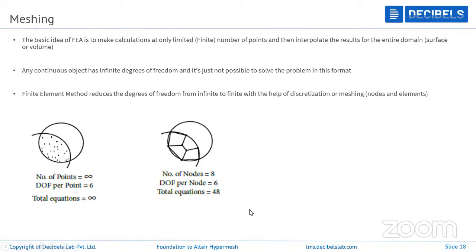We did this in our academics, in the finite element subject, how to calculate the number of equations for a particular surface. When working with truss or bar components, we calculated the number of degrees of freedom, the stiffness, and extracted natural frequencies, all based on the number of nodes and degrees of freedom. Likewise, the software works in the same way. It will calculate according to how many points there are in the CAD, or how many points in the element multiplied by degrees of freedom.